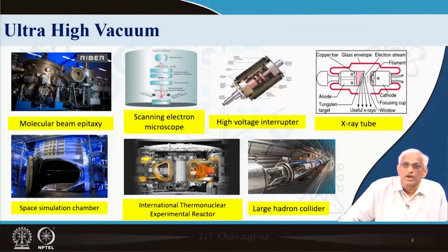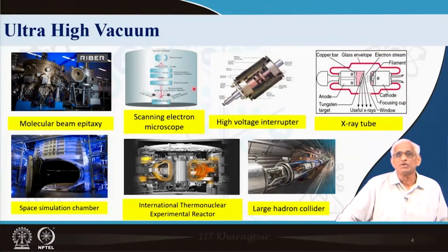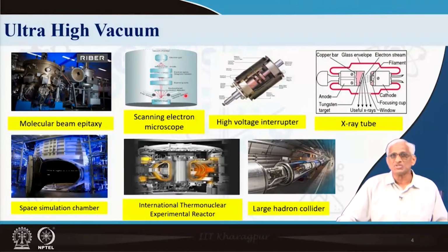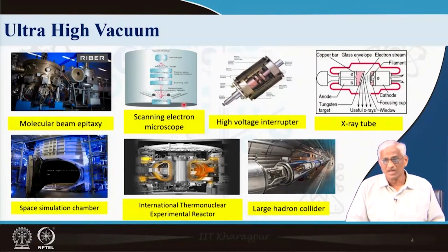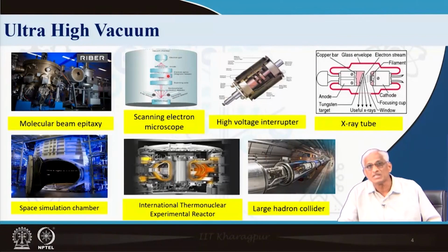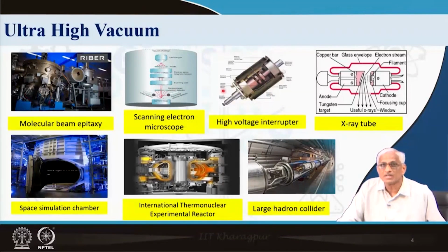And you will find almost every material scientist or metallurgist or any biotechnology, everybody will be using scanning electron microscope, X-ray fluorescence spectroscope, to know the chemistry and physics and topology of it and surface smoothness, etc. All of them will be working under ultra high vacuum environment, because electron beam has to be accelerated by these electric and magnetic fields and arrive at the samples and produce diffraction patterns. It is not possible unless you have a background vacuum which is 10 power minus 8 to minus 9 torr, because beam will be lost. Okay. We will discuss these things later in analytical instruments.